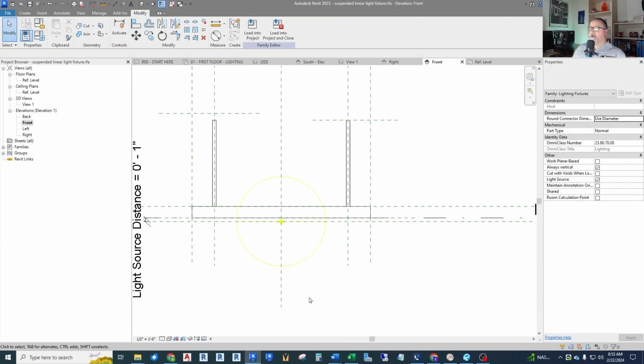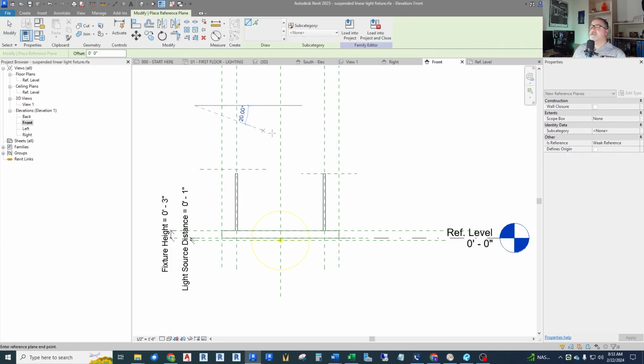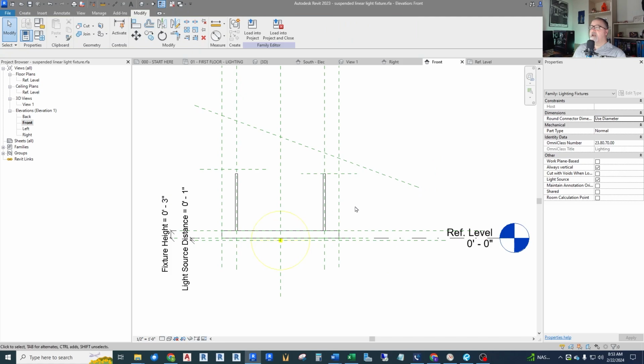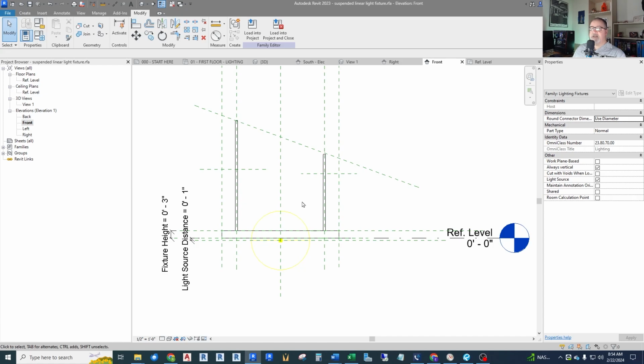Well, imagine now that we're looking at a cross section of a room, and let's say we have a sloped vaulted ceiling, and these are put in this direction. I'll want this stem to hit the ceiling there, and I want this stem to hit the ceiling there. So I'm going to leave these as instance parameters, the height, because each type L1 fixture in my room may be in a different location and need different stem lengths. That is a valid instance by instance parameter. So that's what we're going to do. We're going to make these independent, and we're going to make them instance parameters.